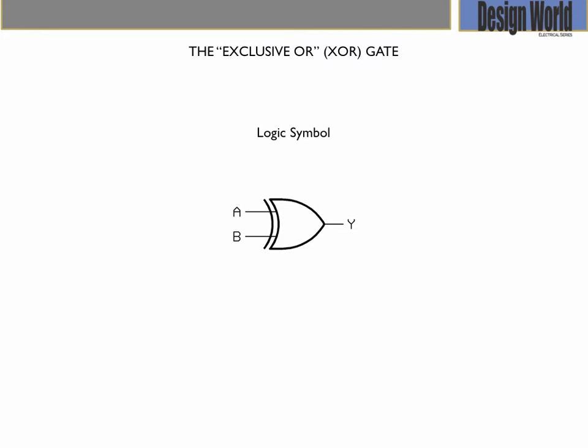The exclusive OR, abbreviated XOR, is similar to OR, but excludes the combination of both A and B being equal to 1. The equivalence is a function that is 0 when the two binary variables are equal, for example, when both are 0 or both are 1. The exclusive OR and equivalent gates are both commutative and associative and can be extended to more than two inputs. The exclusive OR is an odd function. For example, it is equal to 1 if the input variables have an odd number of ones.